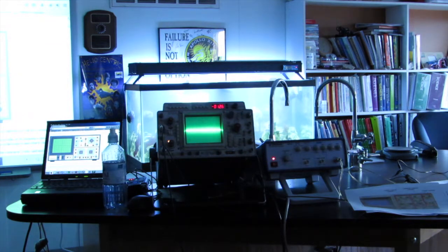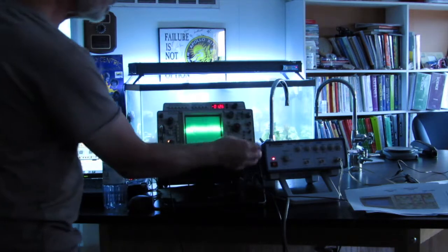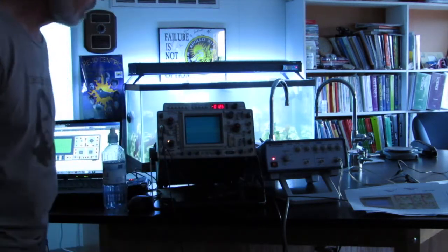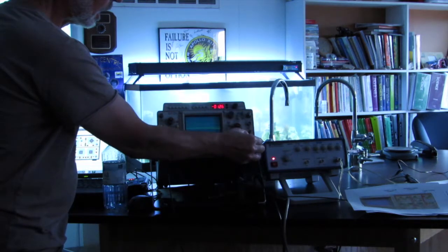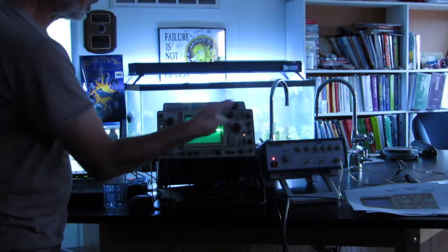Let's say you just wanted to see what that "ha" looks like, and you wanted to capture just the "ha" and not the noise. What you can do is put this on normal, so that you don't have a display, and without speaking at all, if I move this trigger, okay, the trigger is set right at the baseline.